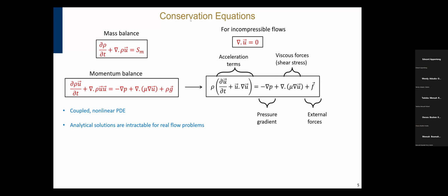Your time step size might be too large, or your meshes are not well refined. If you have poor quality meshes, you end up with divergence because those equations give you a very bad condition number in your matrices. So yes, the mesh is one of the most important things. Apart from the physics, you have to actually deal with the mesh. Make sure that you've refined your mesh. If you're getting divergence problems, the first place to look at is your mesh.